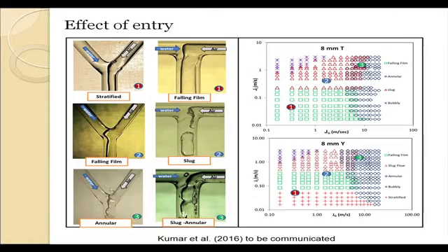So with this it is quite evident that the entry section does have a remarkable effect, particularly, again I should mention, in the mesoscale, and the effect is much more pronounced for lower velocities where inertial forces are less dominant. And in the process we have actually come across a completely different flow pattern, the stratified flow pattern.